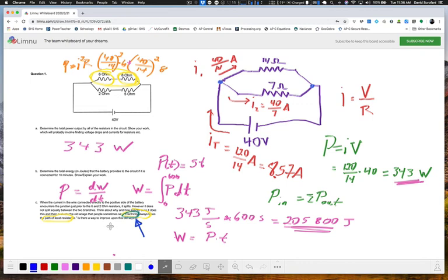The current, the actual charges themselves, the flowing of electrons, the moving charges follow the path of least resistance. And while in this diagram up here, I'm certainly not talking about electron flow because I'm using conventional current models, I think for our purposes it's sufficient. So is it true that current always takes the path of least resistance? Certainly not exactly, right? Because in the diagram you can see that there were two paths at this node point right here, and the current didn't just take the path of least resistance. It took both paths, right? Some of it went on the top through the top branch, some of it went through the bottom branch.